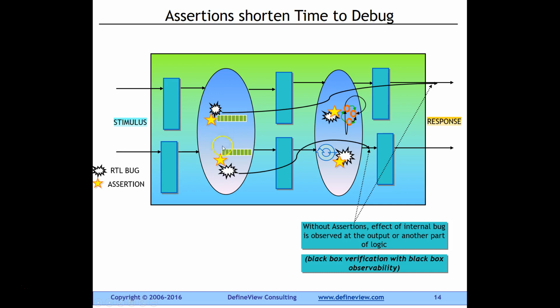So you write all these different kinds of assertions around the state machines. For example, a state machine check could be that state 3 must go to state 2 and not vice versa. For example, state 2 cannot go to state 3. So you have these assertions embedded, and now the test fails. When the test fails, one of these assertions is going to fire.